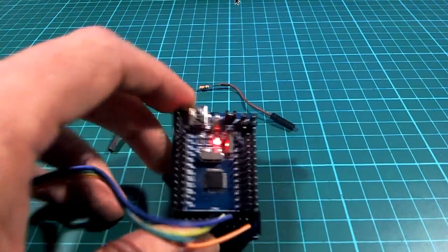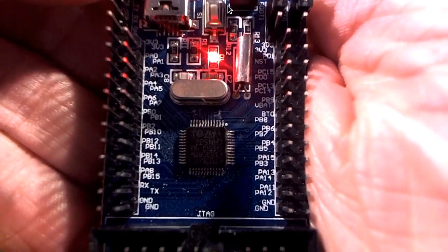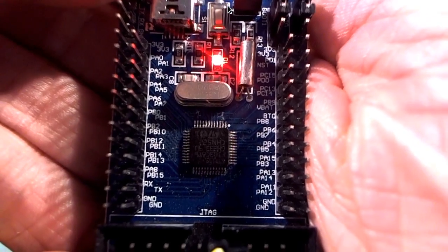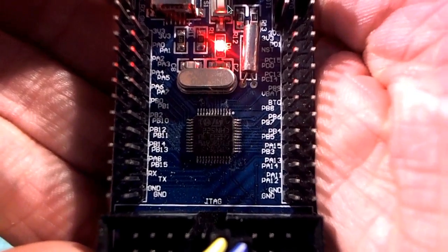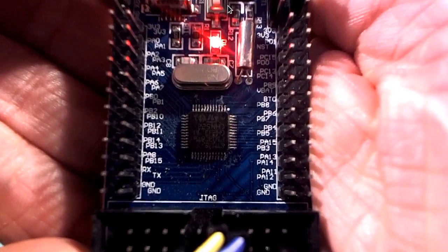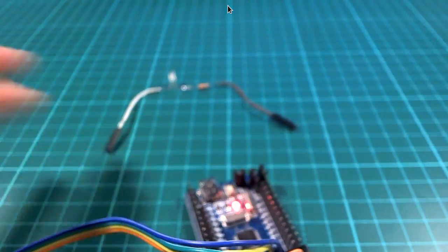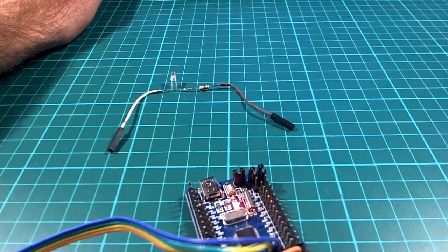Anyway, so what can we do about this? Well, I did notice that we had some other ports that had 12s on them. So in the bottom right, you can see there are 2 ground pins on that last pair of pins, and then there's PA11 and PA12. So I decided to just use PA12 there instead of PC12.